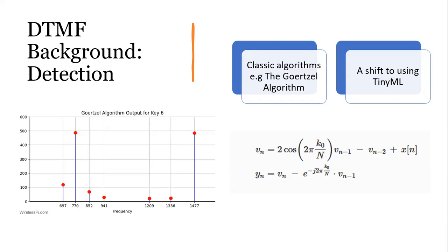You do that by focusing your attention on that particular note and counting the number of times that note is being played in the song. So in a similar way, the Goertzel algorithm works by focusing on a particular frequency in a signal and also counting the number of times that frequency appears in the signal. And if it's able to detect a chunk of that frequency, then it can conclude that that frequency is within the signal.